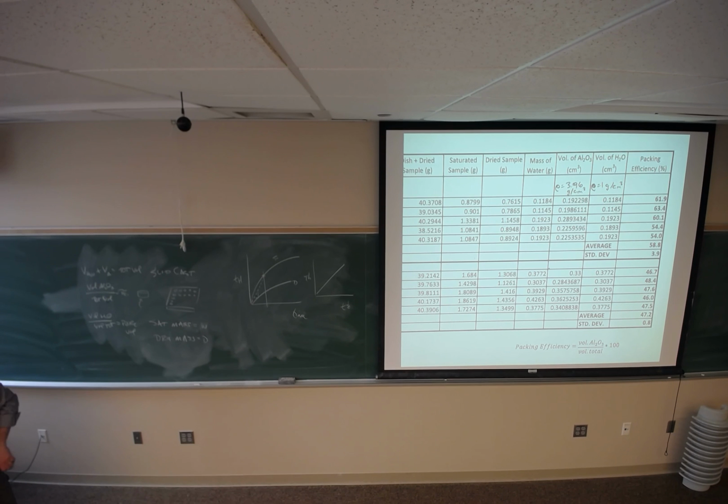How do you get around the problem? How can you speed up the casting rate for dispersed? You go to higher solids loading, right? Make a more highly concentrated suspension, and your casting time would be shorter. You could also cast a smaller pellet.